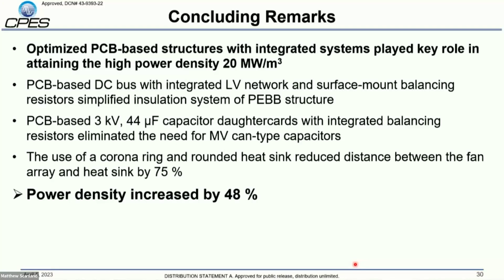So the takeaways from this is really that we can use the PCB-based bus to integrate several of the features that we want to get out of our medium voltage converter. Using the E-field-based design approach, we can significantly shrink all of our requirements. And using the capacitor card approach, we can get higher capacitance in smaller volumes.